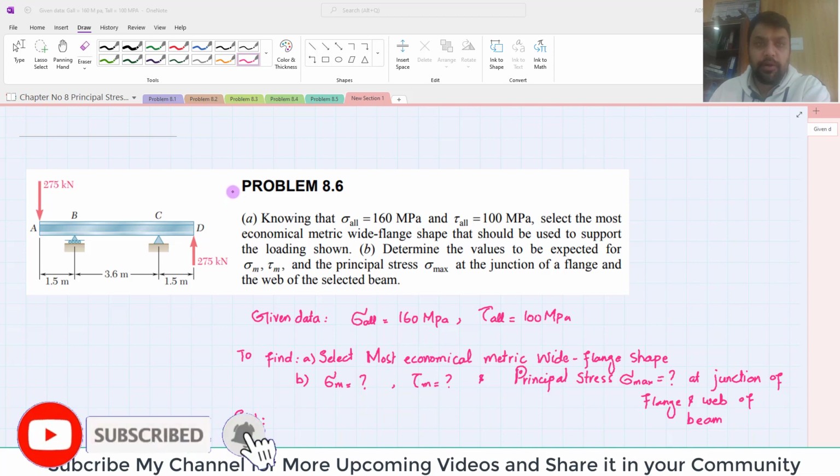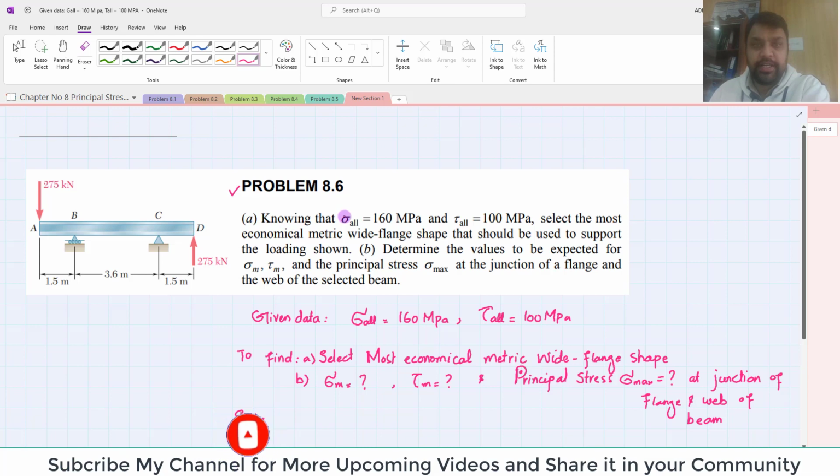Bismillahirrahmanirrahim. Welcome back. Problem 38.6. The statement is that sigma allowable is 160 megapascal, and maximum allowable shearing stress is 100 megapascal. You have to select the most economical wide-flange shape that should be used to support the loading shown. This is the loading shown on the overhanging beam.